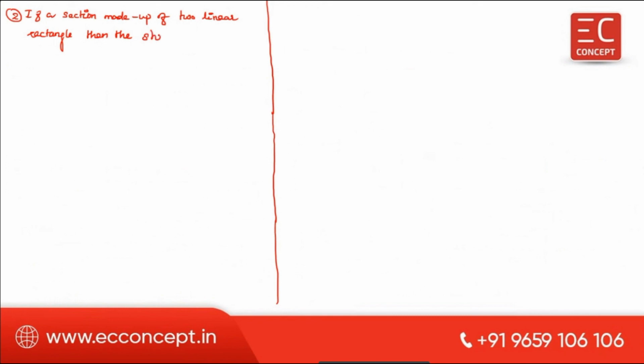Now the second point. If a section is made up of two linear rectangles, then the shear center lies at the meeting point of the two rectangles' centroidal axes.